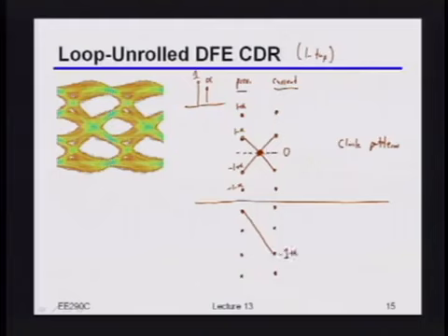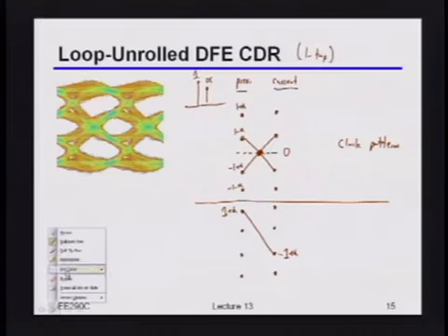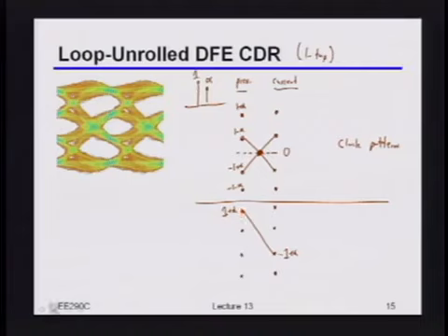And again, just to be clear, this would happen because I get the plus alpha here because the previous bit was a 1, right? Okay, so what's the symmetric arc that you would get? Like if I just flipped everything over, what's the symmetric arc? -1 minus alpha to 1 minus alpha. Yeah, exactly. This would be just -1 minus alpha to 1 minus alpha. Okay? Turns out there's actually a couple more transitions that we can get, but those maybe are not as interesting. We'll come back to them in 1 second.